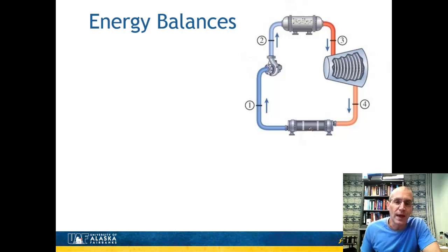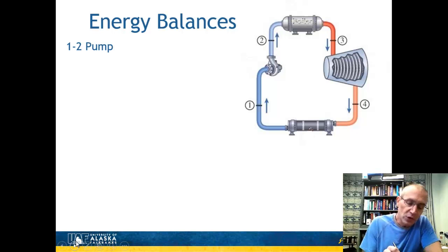So let's go ahead and look at the energy balances. And I say energy balances because there's essentially a balance over all four of these components, and then we can do an energy balance around the entire cycle. So we'll take these one at a time. Let's go ahead and look at the pump here. As I said, we know pumps require work, so there's going to be some work that goes into the system. And what this does is it increases the enthalpy.